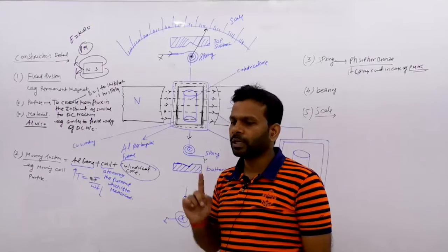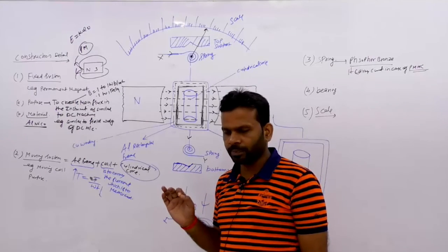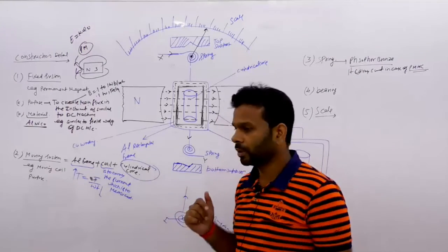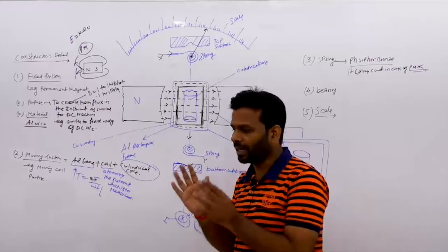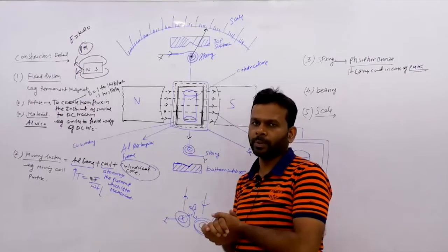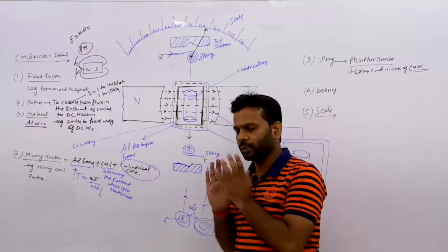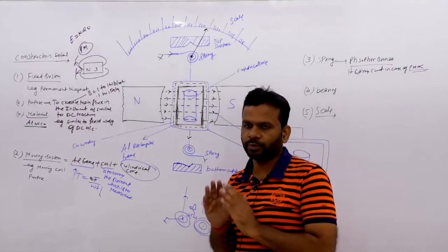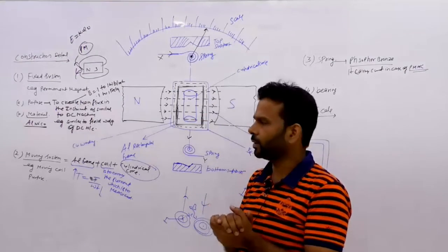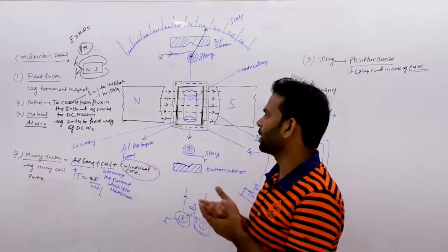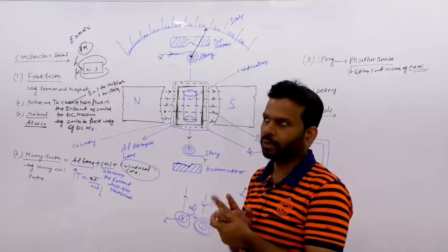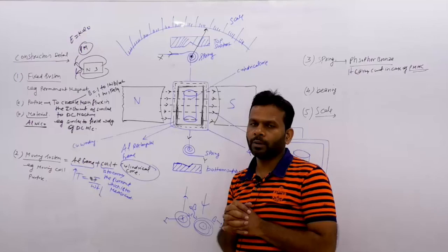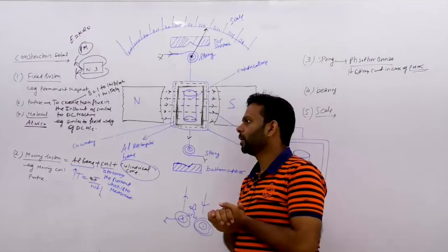Air damping, because in case of the MI system, in case of the moving iron system, the fixed system is air core. That's why the magnetic field is lower as compared to your PMMC instrument. That's why in case of an MI instrument they use air damping, but in our PMMC instrument we use eddy current damping just because of the high magnetic field provided by the fixed system. Now it is having the highest magnetic field, so no need for shielding. But in general, the shielding material is nickel ferrous, NiFe, nickel ferromagnetic material use करते हैं हम shielding के लिए.